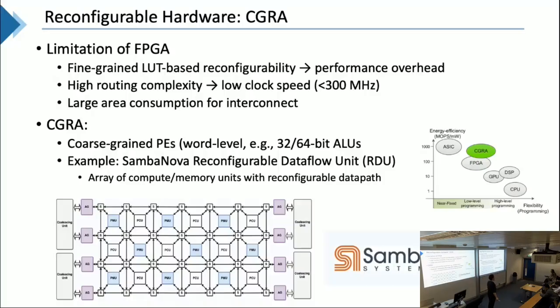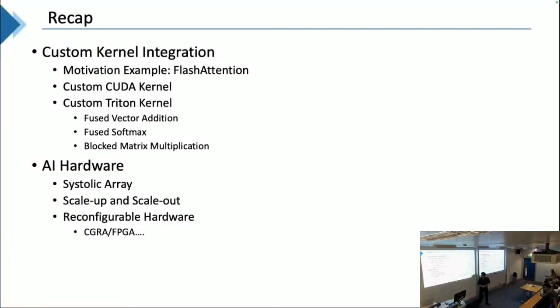So you only have a limited choice for the reconfiguration. For example, you can reconfigure this unit as matrix multiplication and reconfigure this unit as other operations, but it's not a general Boolean function, which loses some flexibility and generality. And if you look at the connection, it's also less flexible than the FPGA, because in FPGA we have a very large gray area for this reprogrammable interconnect.